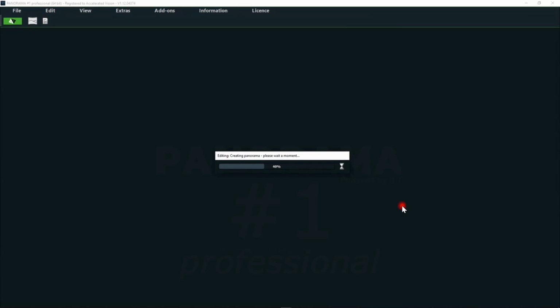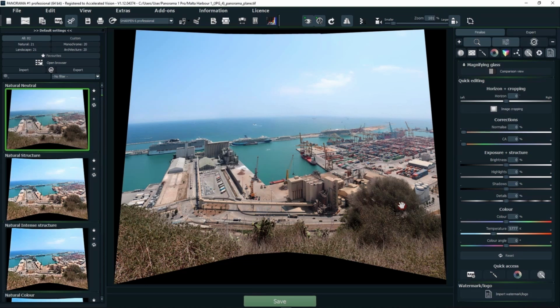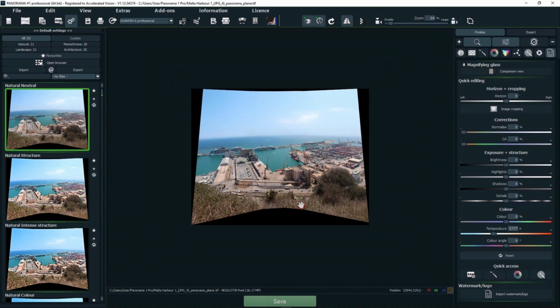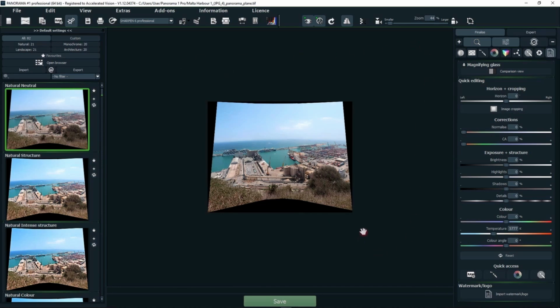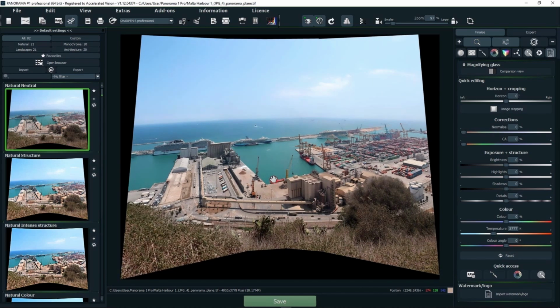And then we'll see what this kind of planar projection looks like and why you shouldn't use too many images in these planar projections. We can notice the effect a little here. The images in the middle are slightly compressed, and the images on the outside are pulled apart or projected apart, but with straight lines. And if we zoom out a little here, if we had another image to the left and right, we would already need roughly all this area because those images will go down at a very sharp angle here. With that in mind, I want to say right from the start, if you're using planar projections, please either use a computer with enough RAM, so 16 gigs or more, or just use a few images.